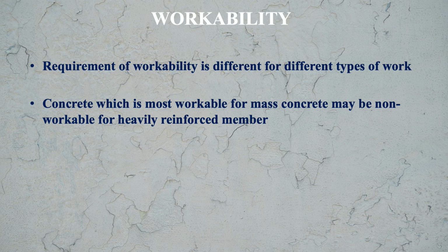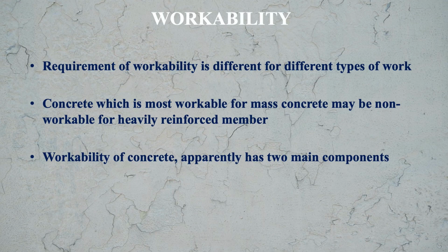Concrete which is most workable for mass concrete may be non-workable for a heavily reinforced concrete member. So for all works you cannot have the same workability of the concrete mix. As you just saw, the concrete mix which is workable for mass concreting work may not be workable for a heavily reinforced member.